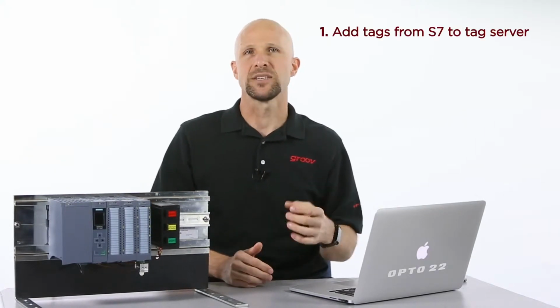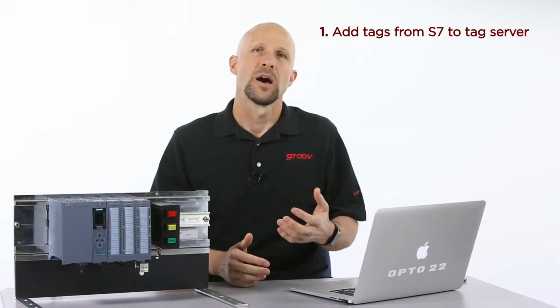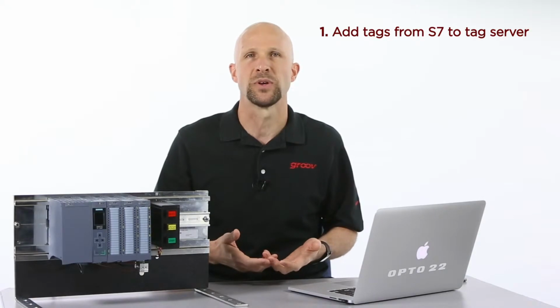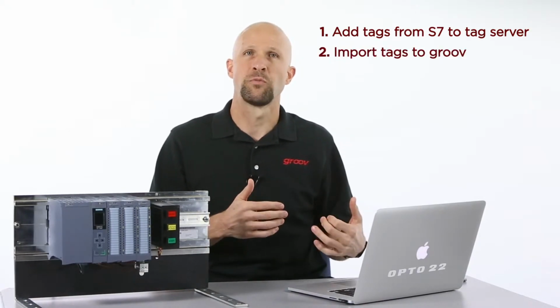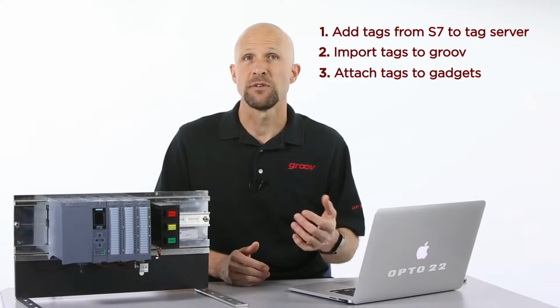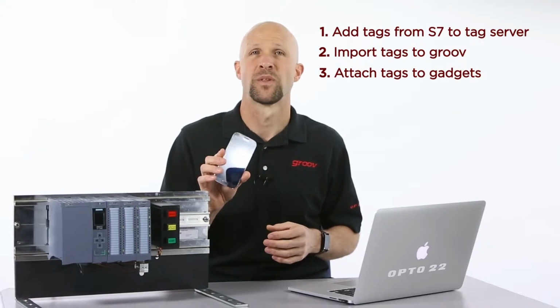First, I'll enter the S7 tags I want to see in Groov into my tag server. I'm going to be using Kepware's KEPServerEX installed on a Windows computer. Second, I'll add the tag server into Groov Build and import those tags. And third, I'll attach gadgets to those tags, then save and view the data on my desktop web browser and on my Samsung Galaxy S4 smartphone. So if you're ready, let's get started.